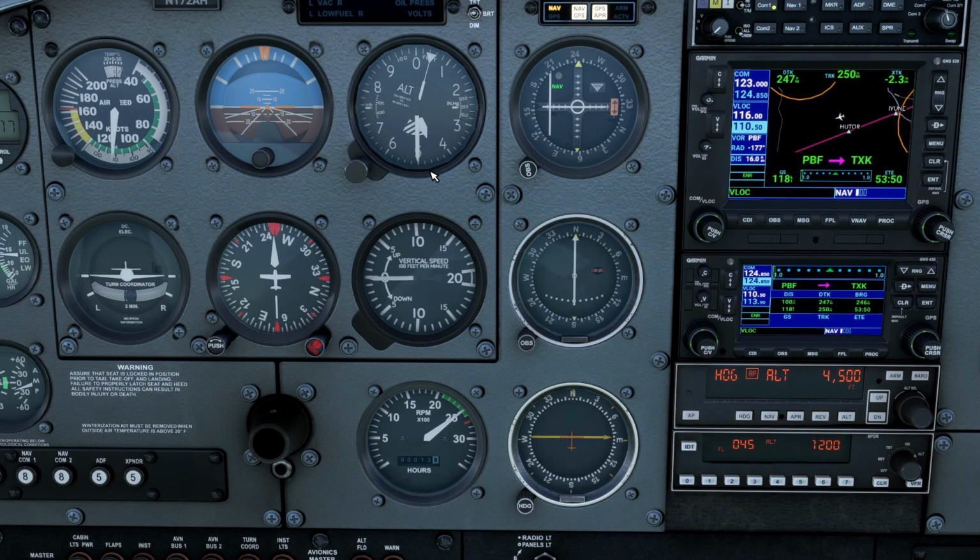So one thing that the autopilot in Flight Simulator, at least on this airplane, does not do well is intercepting of courses. Particularly for VOR courses, it uses an overly aggressive intercept angle that you can't control. And then because of that, it starts doing S-turns about the radial once it's kind of gotten itself on course. I've set up a little demonstration to show you what I'm talking about here.